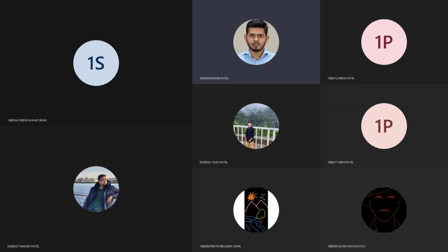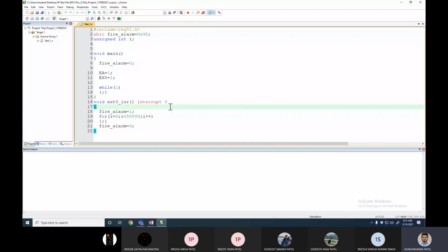In the fire alarm with 8051, a smoke detector is connected to the interrupt pin. So I can program 8051 in interrupt mode. Keep that in mind, I am using external interrupt here in this program. We just enable that interrupt using these two lines of code. Whenever there is a falling edge or a low level on the external pin, at that time my interrupt will trigger.